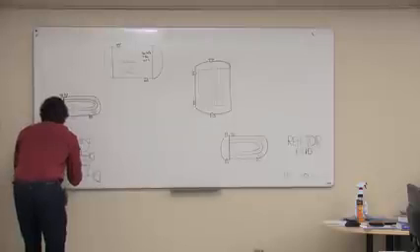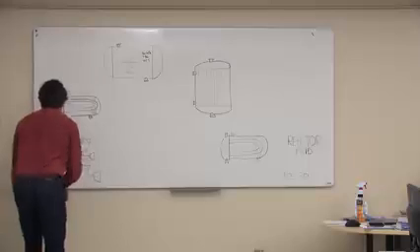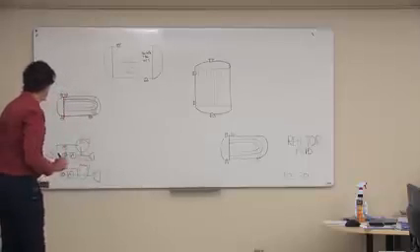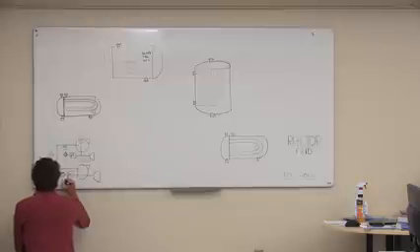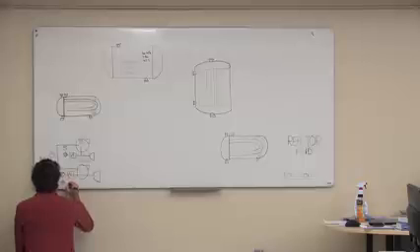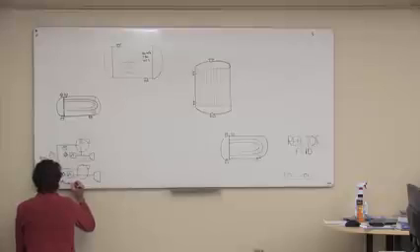So that's an HS in a balloon and a dashed line from the HS down into the interlock. So that gives us the ability to start and stop the pump and also to put it into auto. So we're going to write on, off, and auto.